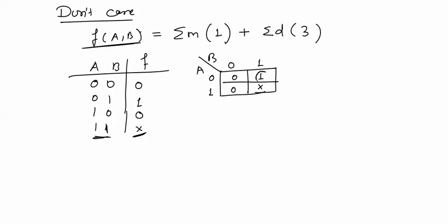This is a single one, and we could form a single, but according to the definition of K-map we should make a pair or combination of the largest size. So this don't care adjacent to the one can be used as logic 1 and a pair can be formed instead of a single. So the expression for f can be written as f equal to b.